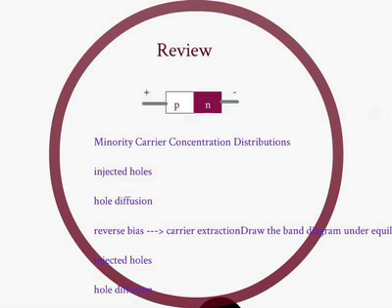And this is the reverse bias, but once the minority carriers reach the junction, they just get swept across by the electric field, the reverse bias electric field. These are minority carriers. Holes in the N-type will get pushed across to the P-type because it's reverse bias. So the only main thing we need to do is solve the diffusion equation here. And by knowing the recombination current, we can calculate the base current. That's the idea.